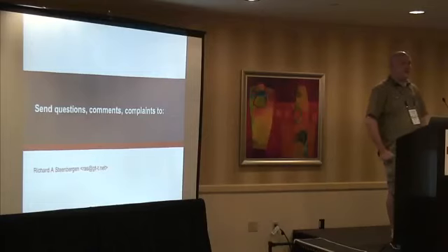If you've got complex rings, OADM, things like that happening, it becomes a lot more complicated than just a simple point-to-point system. Most people can figure out a point-to-point system very quickly, and most of the time it actually works out very well. But when you start getting into OADMs, when you start getting into amplifying, maintaining the network correctly to do that, that's when it gets tricky.